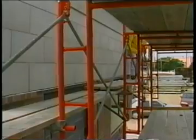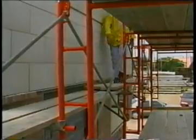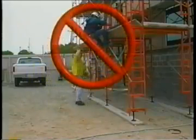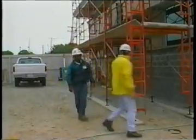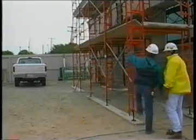It is the responsibility of every worker to look over the scaffold before you use it to make sure you are not getting onto something that is unsafe. There must also be a safe means of access to scaffold platforms. The ladder may be built into the scaffold, or a properly secured portable ladder may be used. No one is allowed to climb the cross braces.